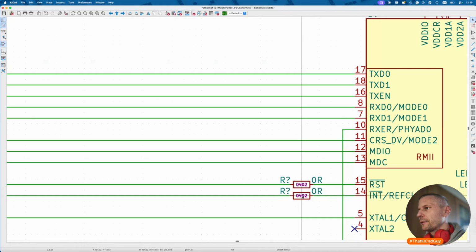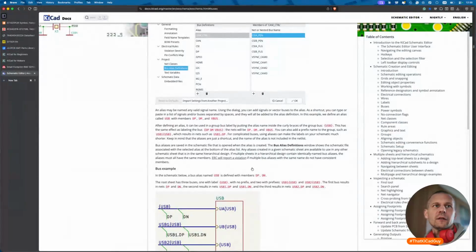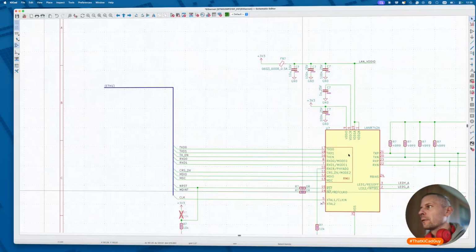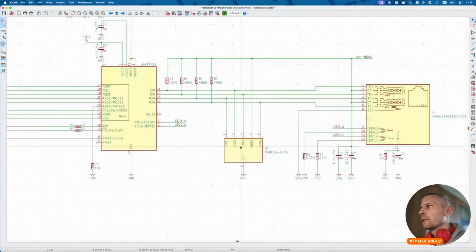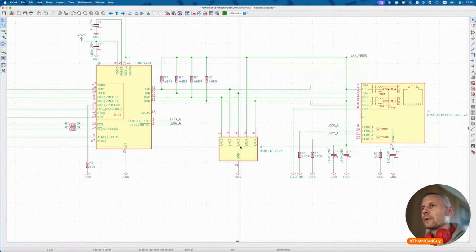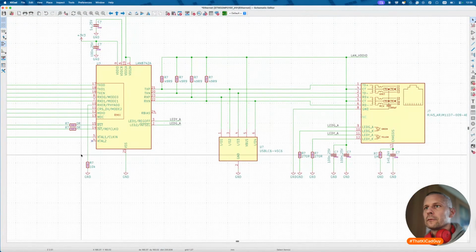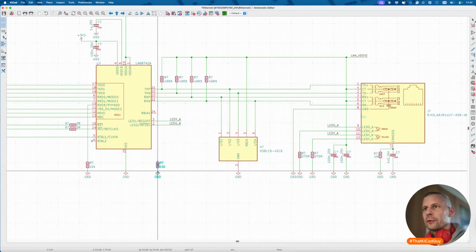Reset and interrupt, I'm just checking whether all are populated. The 10K from the anode is unpopulated. Let's do LED 2, it has an unpopulated resistor to ground.